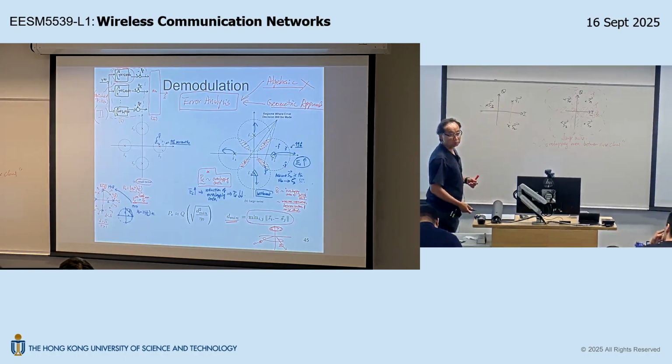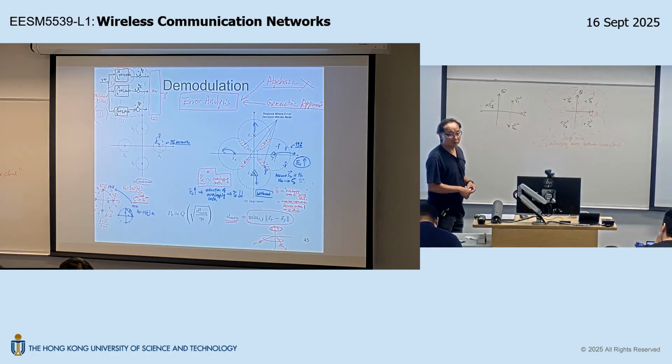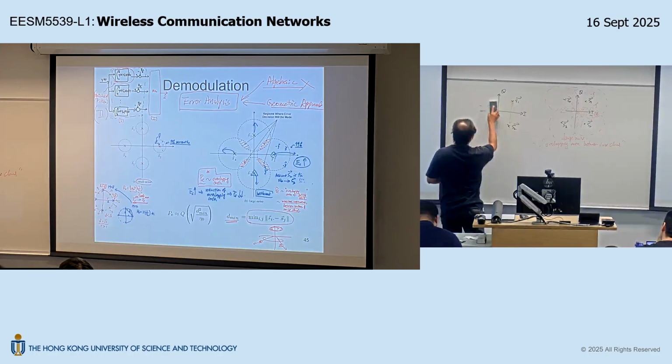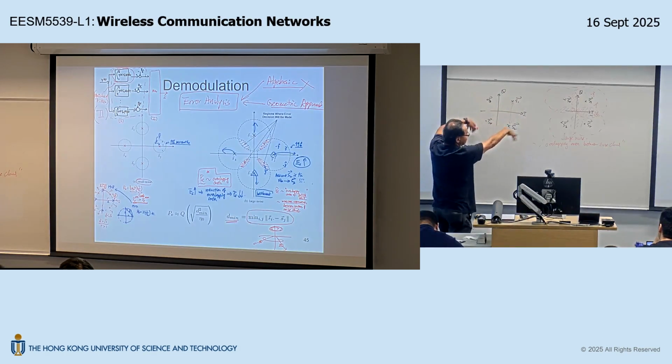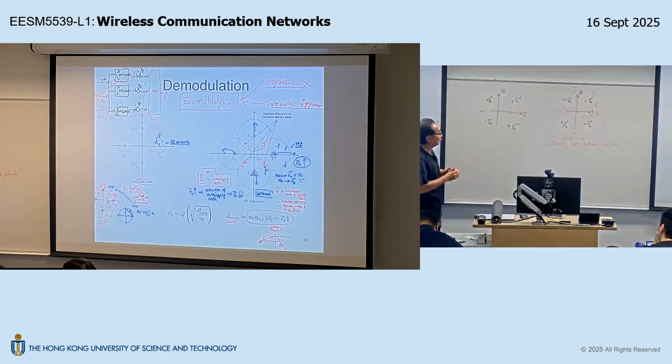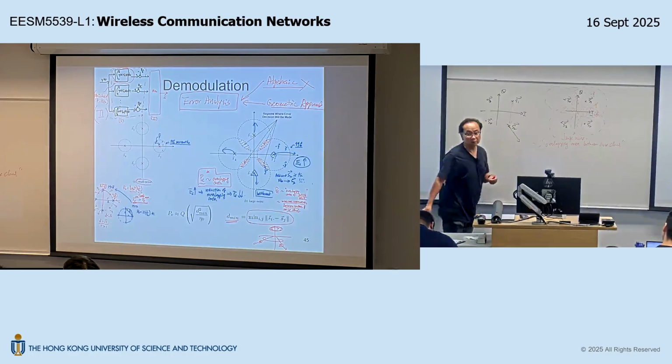Now, if I have 3 points in my signal constellation, then we are talking about multiple overlapping areas, right? We are talking about the overlapping areas between these two noise clouds, these two noise clouds, and these two noise clouds, right? Or do it this way: if I have 4 points, and then this is S4. So imagine you have a noise cloud centered about each of these points. Okay, I don't want to draw the noise clouds here. Now, if you try to spend some extra energy and just move this point, this noise cloud, away, will this help?